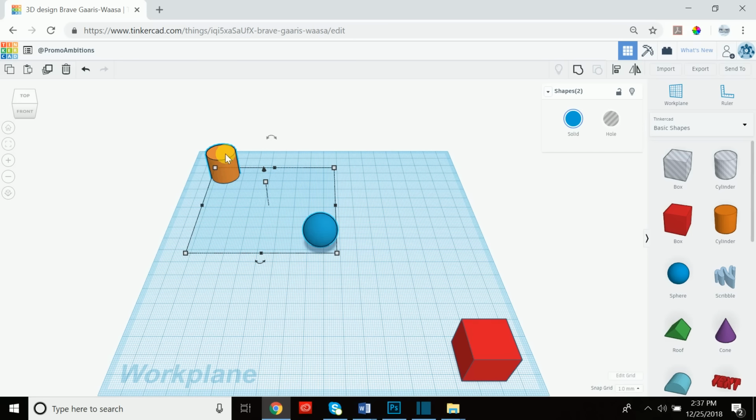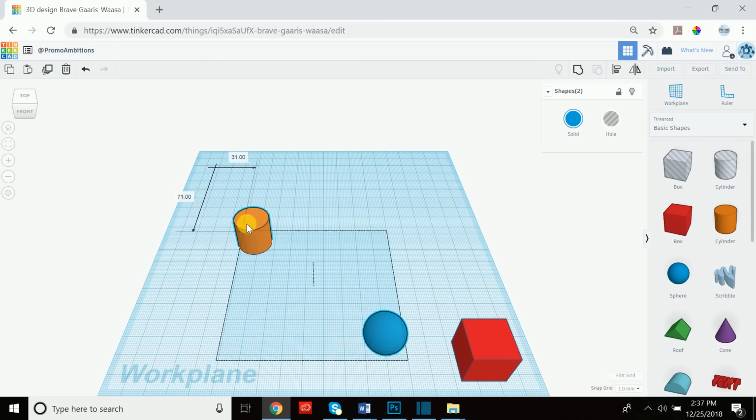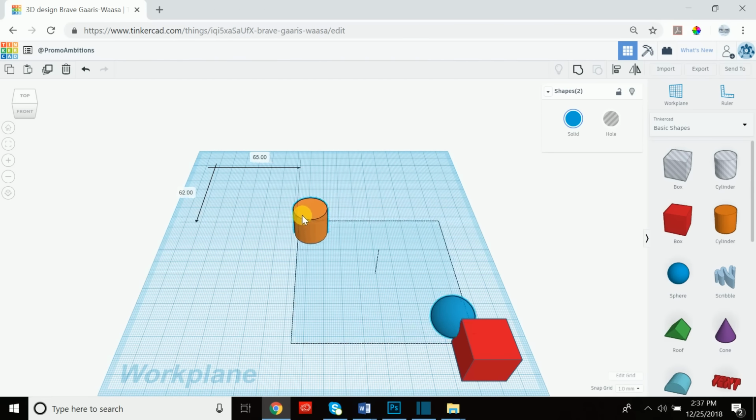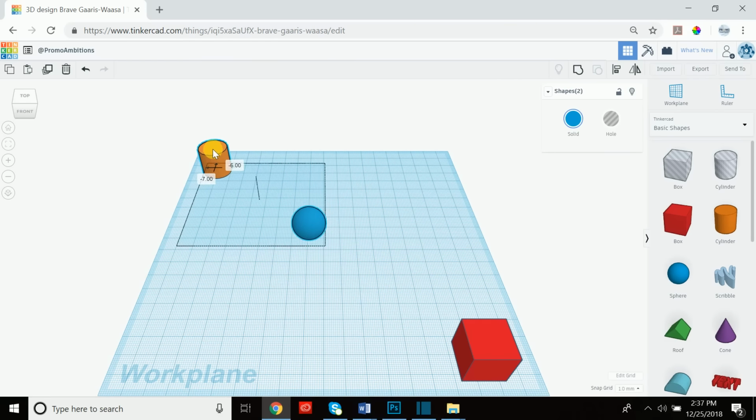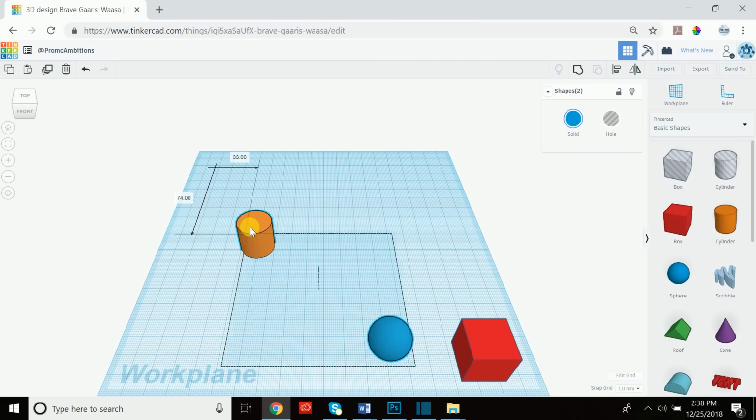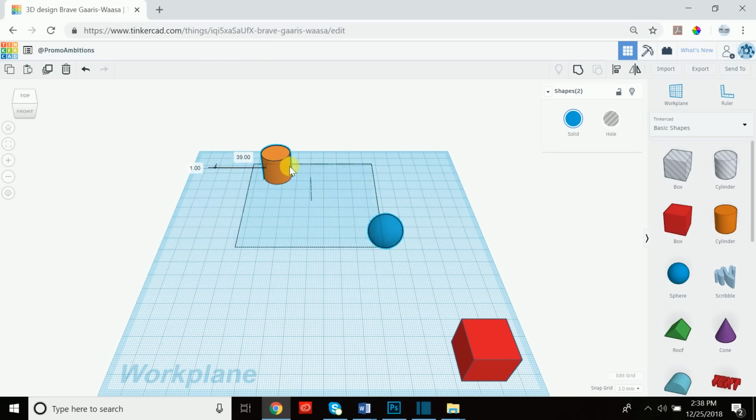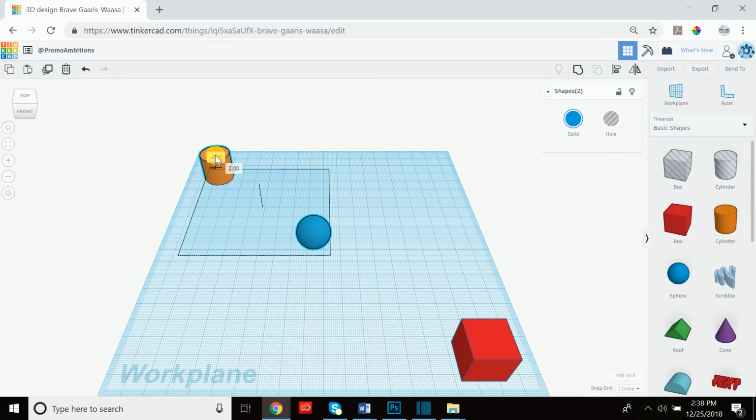You can test this by left clicking while the mouse is hovering over one of the objects, holding and dragging them around, and you'll see that now it moves both objects. It doesn't only move both objects, it keeps the relational distance to one another as it moves them, which is very helpful. To deselect items, you simply click anywhere outside the items and then everything is deselected. So back to this section here, and we're going to cover each of these sections individually.